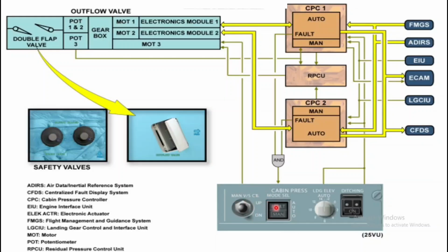If you talk about the mode selector push button, the manual motor is used in case of failure of system 1 and system 2. Then on the mode selector switch, you will get a fault light also, and you can select MAN. You will see there is a MAN word. Once you select it, it will be commanded through this toggle switch.